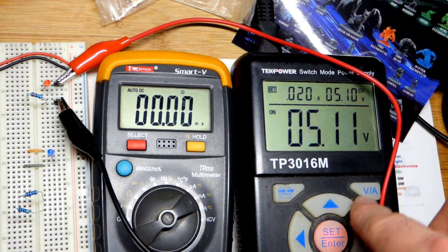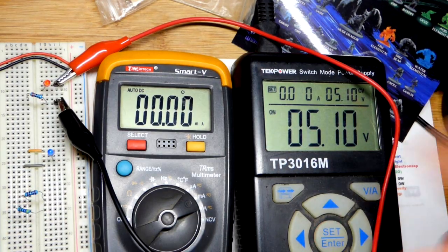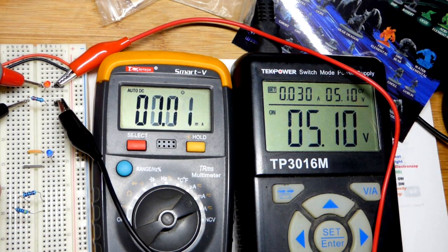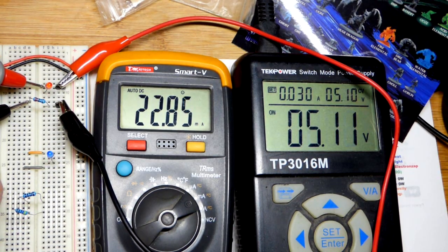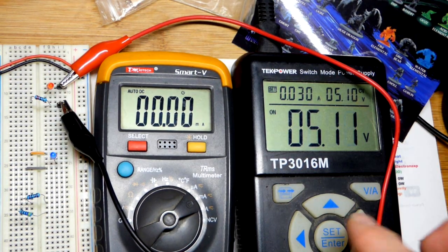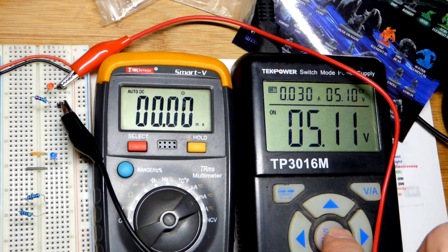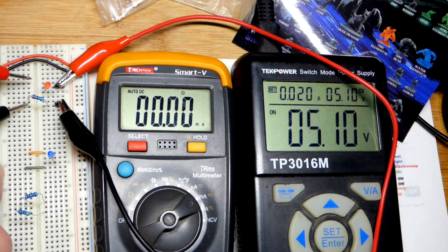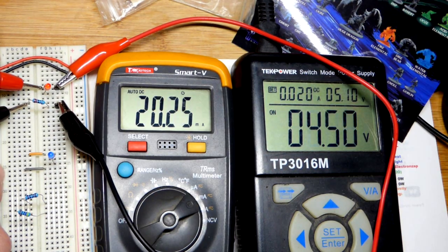That's why we got that protection. Now, if we want to see the actual current flowing through the resistor, I can set that up to about 30 milliamps of current, which if we put through the LED for a brief period of time, probably would not damage it, as long as we kept it really brief. But there you can see, now we got about 22.86 milliamps of current. So that's one way I do troubleshooting: if I get the maximum current right there on the power supply, I know that I either short-circuited something or something like that that's causing more current than I want.